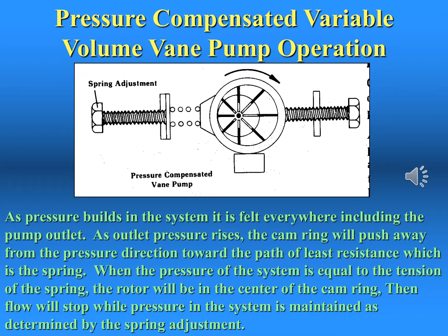The schematic symbol does not tell the reader which type of pump they are looking at, only its function. Due to greater internal lubrication of moving parts, these kinds of pumps and motors require that the case be constantly drained in order to prevent internal pressure buildup, which could damage the shaft seal. Whenever a pump is replaced, it's always a good idea to check this drain line for blockage.